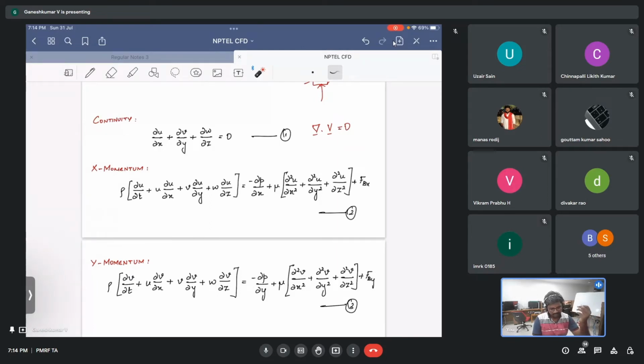So where does this Navier-Stokes equation come from? If we look at this part closely, it is actually density times acceleration. Look at dou u by dou t, the time derivative of velocity, it's a kind of acceleration term. Density is a kind of mass term. So this part of the equation is actually mass times acceleration, and the other three terms are the forces.